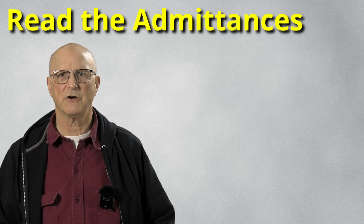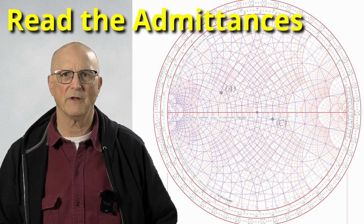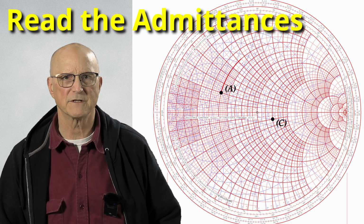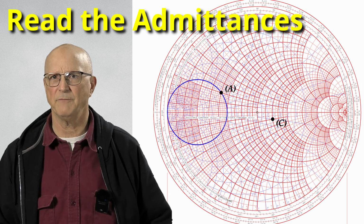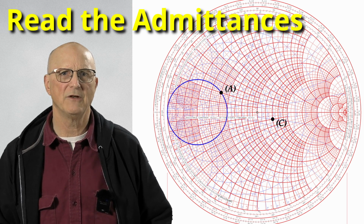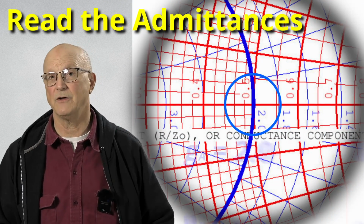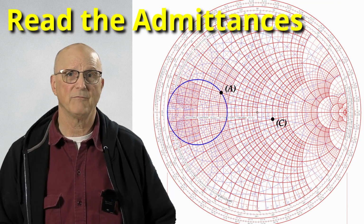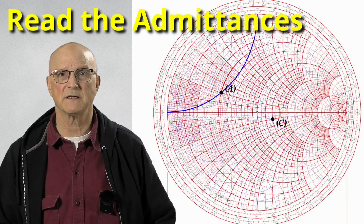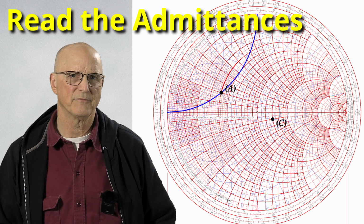To do this, I turn my attention to the blue lines. Let's look at the normalized source impedance dot first. I find the blue constant conductance circle that passes through my dot and note its value. I see here a conductance value of 2.0. Then I find the blue constant susceptance arc that passes through my dot and note its value.